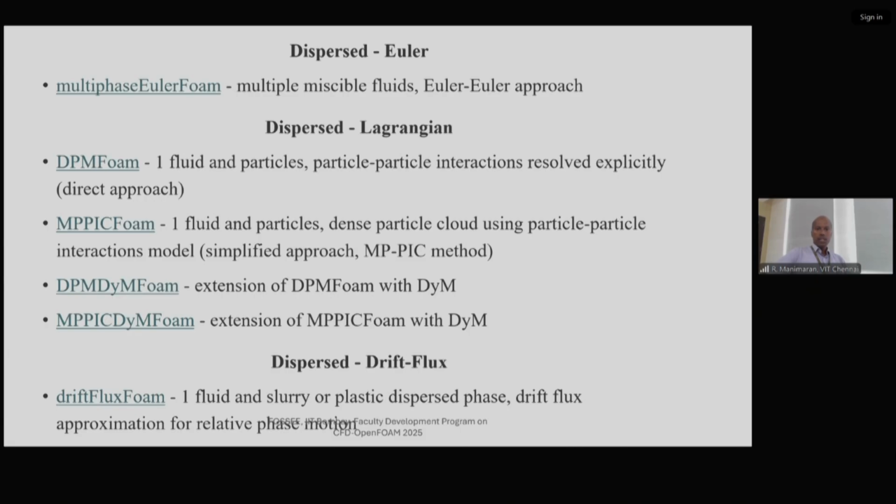Then we have the dispersed Lagrangian type. One is DPMFoam, which stands for discrete particle method. One fluid, and particles are taken care of. Particle-particle interactions are resolved explicitly. It is a direct approach.